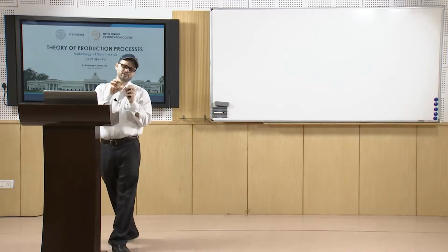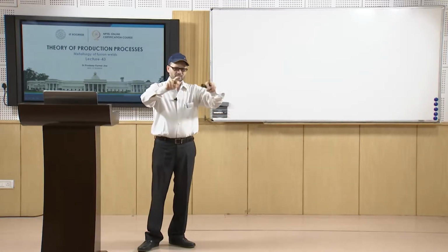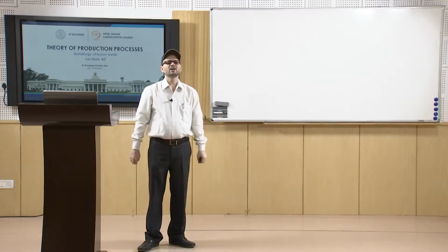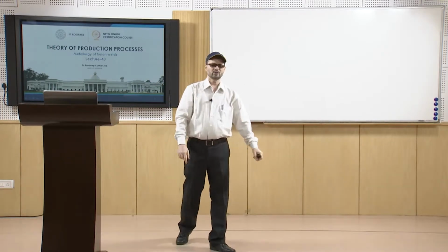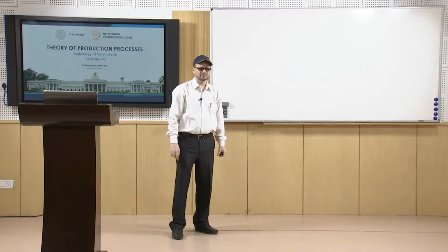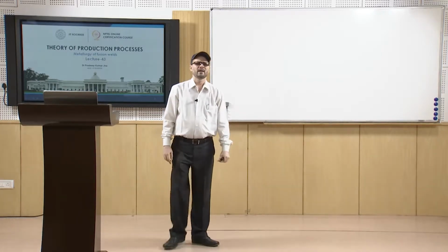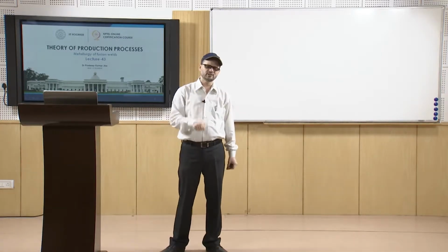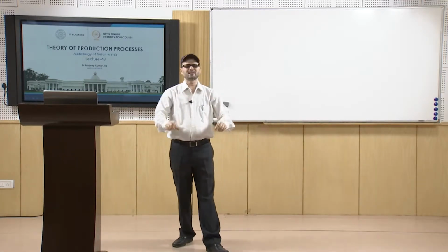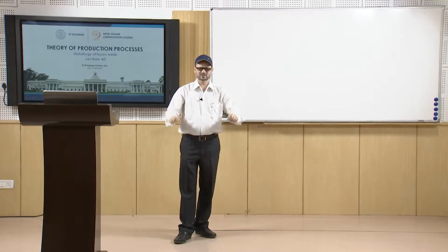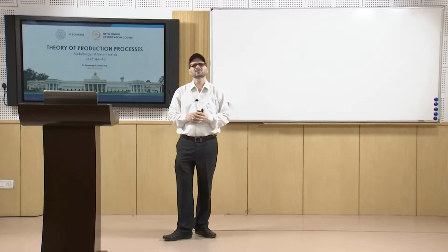If the welding velocity is less, there will be more transverse spread of the isotherms, and similarly if the speed is more, there will be less spread of the isotherms in the width direction.